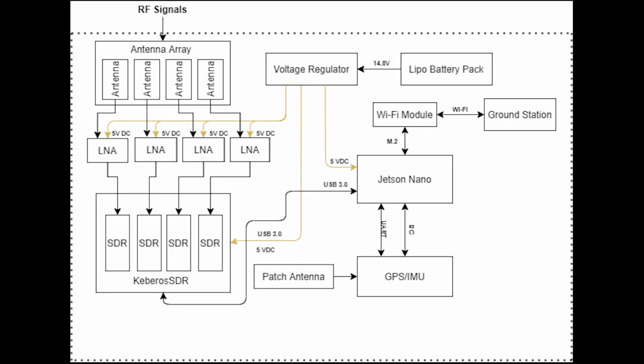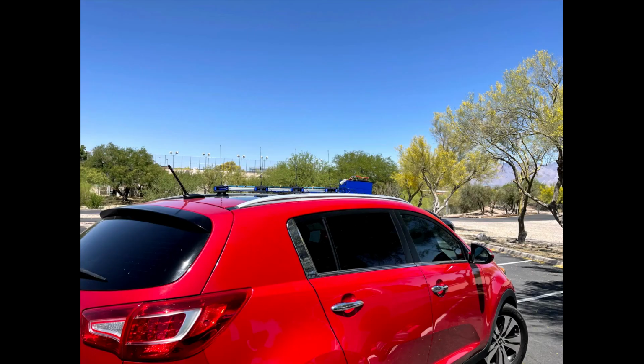One of the concerns at the beginning of this project was that the reflected signals from the TV stations would be too weak to be able to pick up with a software-defined radio that only has 8 bits of resolution, which is why the low-noise amplifiers are built into our design as a precaution. But after initial testing, this turned out not to be an issue. In conclusion, the system we built is able to image direct path and multipath reflections.